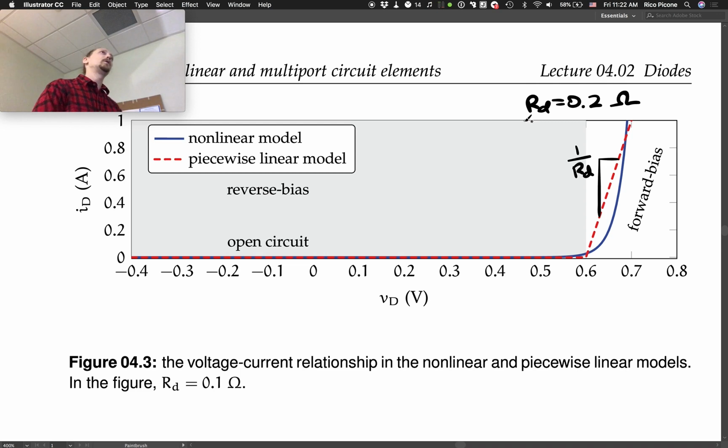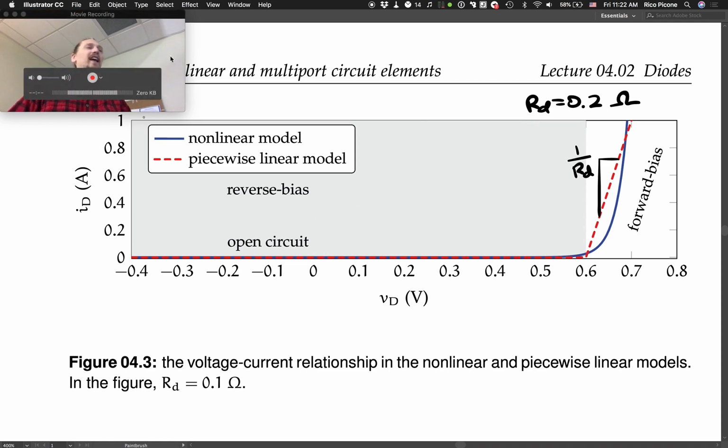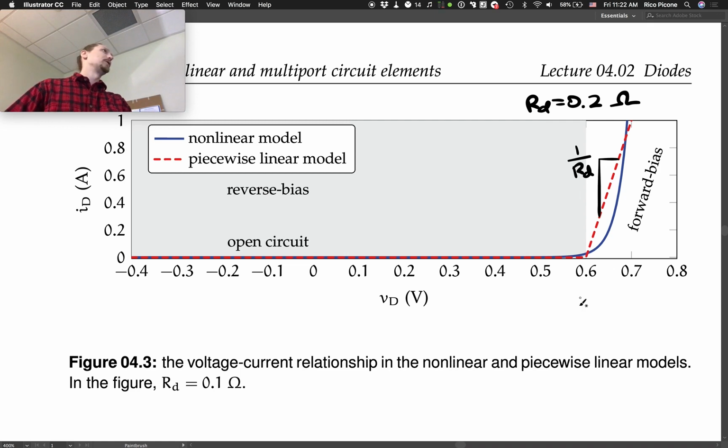It's good to, at the end, go back and check how close was I to the operating regime, given the solution, given the assumption that I made? And you can iterate a little bit if you want. So you could get a solution and say, wow, the current was actually like 10 amps running through this thing, and my diode voltage was out here like above 0.7, and so I needed to have a much more significant slope.